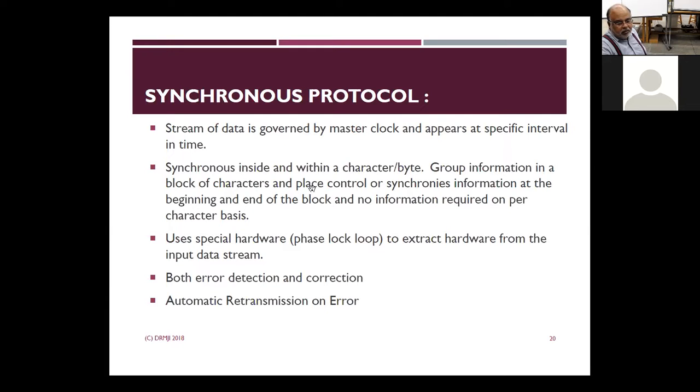So in that case, you don't have to send just a byte of data. You basically send a block of characters called a frame or a packet. So you can send a complete frame of data. And now the question is, do you send a separate wire for clock? That's the big $100 million question. Do you send a separate wire for clock? The answer to that is no. The clock is basically embedded within the data.